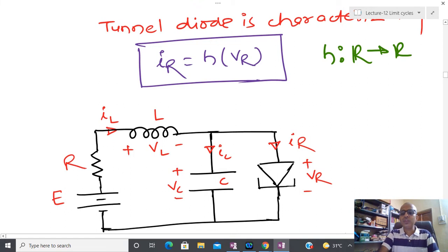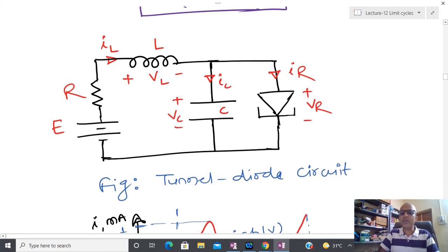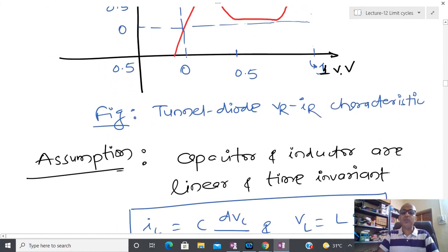Now what I am going to do is first incorporate one tunnel diode and try to see its mathematical model and do some kind of analysis. Here you can interpret this diode as a resistor only. They are not going to store any energy, we are assuming here. So my order of system remains second order. Anyone has confusion on this point? Here you can see that I have a constant voltage battery source, and a resistor, L and C, so I have connected an RLC circuit, and after that I have a diode, that is called the tunnel diode. So please be careful, both are different.